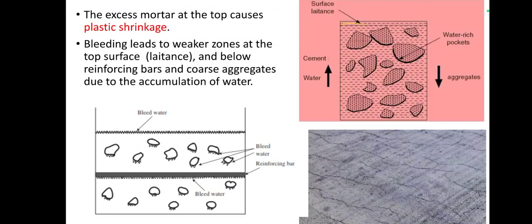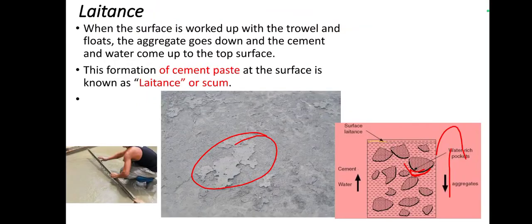Next, it also causes plastic shrinkage. If you add more water, it comes to the top surface and evaporates immediately. The evaporation happens very drastically when we make concrete during midday, so it will immediately form a stress. If restraint is not provided, it will cause a crack due to excessive stress creation. And also, as I told, due to bleeding, wherever the reinforcement is,